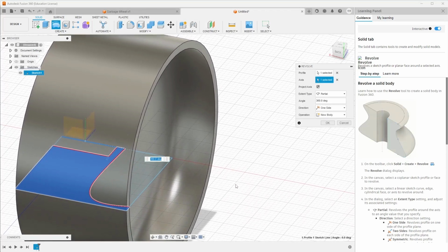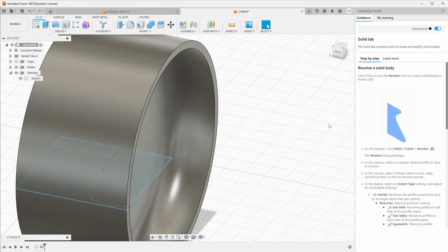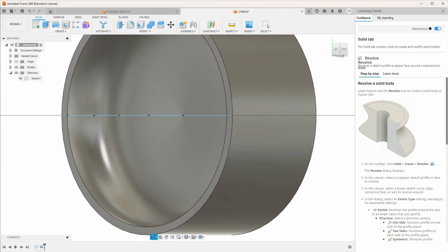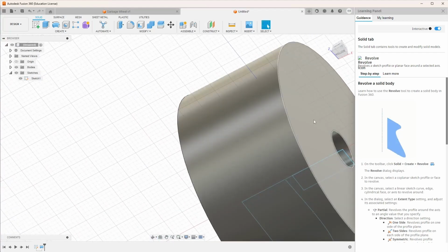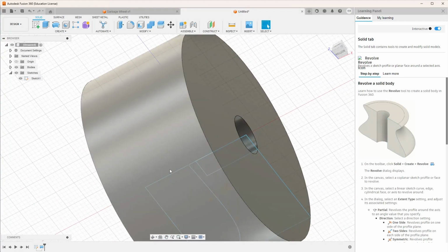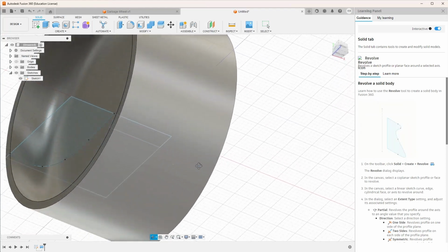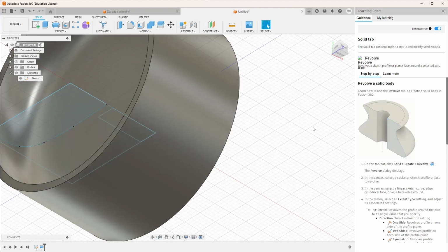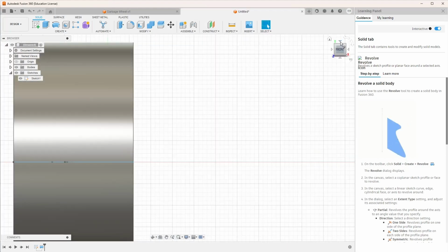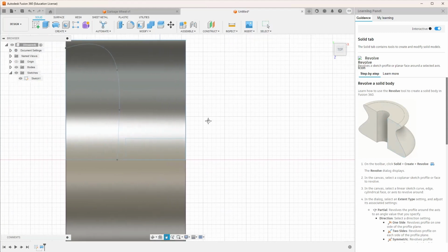It's hollowed out in a way that is completely uniform because this sketch that I made was 1 degree of the 360 degrees as it revolves around. And all 360 degrees are the same as that 1 degree that I made. So what it does is it makes a wheel with a contour like it was machined that way. It still has my hole in the center for my axle to go through, but it has some unique shapes to it now, almost like it would if it was an actual car rim. Pretty neat.